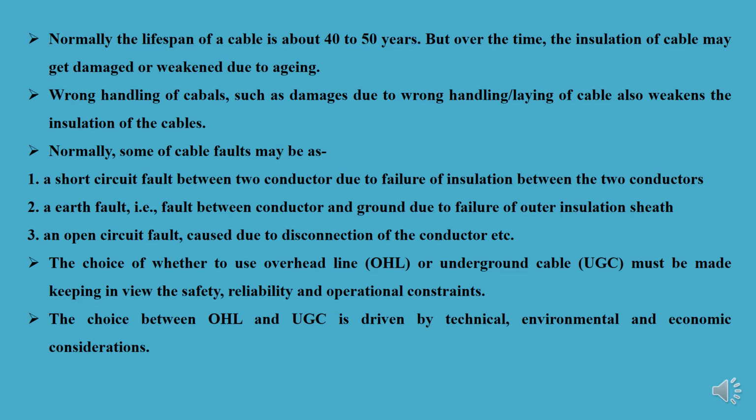Wrong handling of cables, such as damage due to wrong handling or laying of cables, can weaken the insulation of the cables. If you are not maintaining the proper distance, or you are laying cables improperly, because of that also there may be a chance of weakness in the insulation. Normally some cable faults may occur, so there are some faults that we have to understand and clarify.